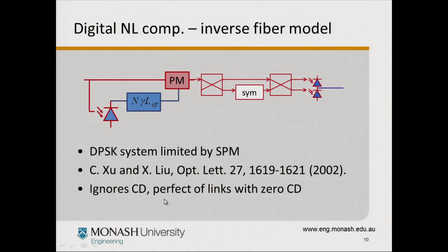So full nonlinearity compensation is clearly not possible anymore, as this is a very big assumption, but the benefits were observed in the experimental lab nonetheless. It's shown to work well for low chromatic dispersion links, that is, dispersion compensated links or links constructed with fibers with very low dispersions.